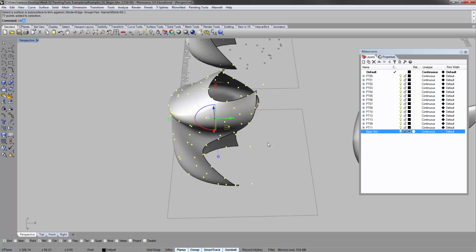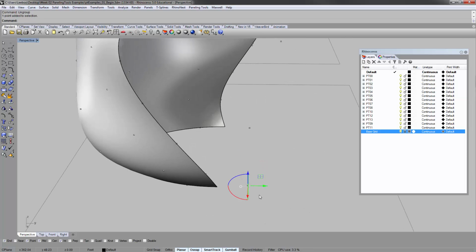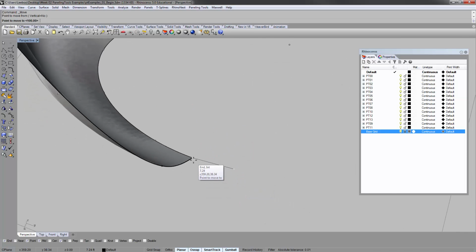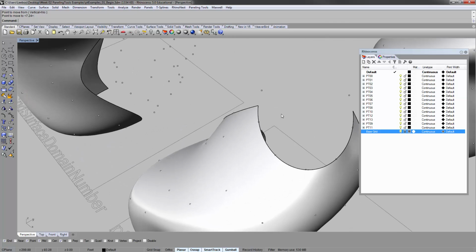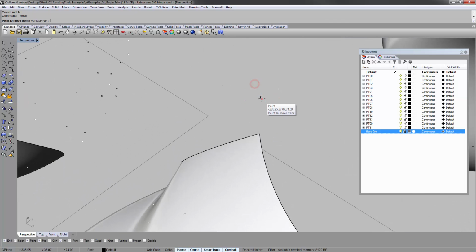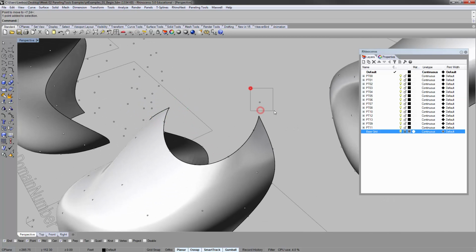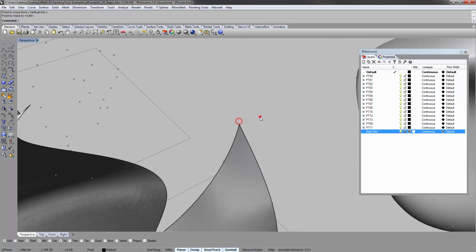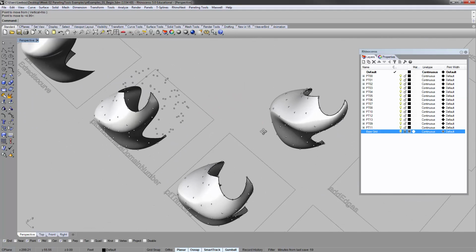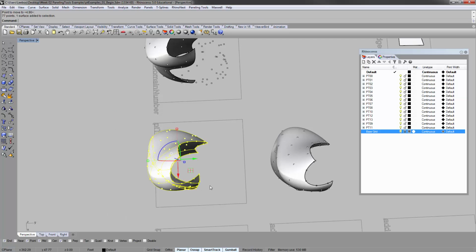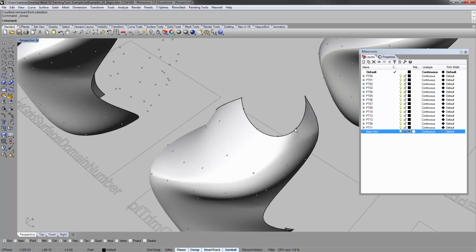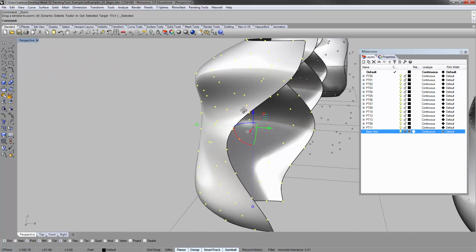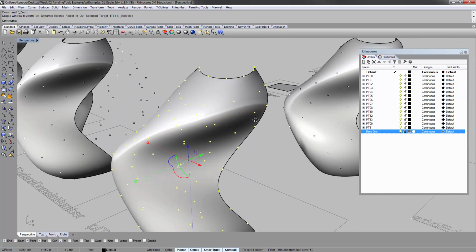What you just need to do is ungroup this points cloud for now, and you can just move this into the right position. So move those points and snap them to the corner of the surface. Just in case that happens, sometimes it will, most times, unless your curvature is really extreme, it won't. Okay, so now I'll select everything here and use my control key to deselect the surface and group it back again. So this is still a valid points grid. All right, pretty simple.